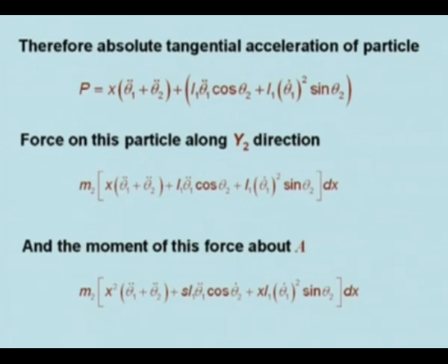Now the force on this particle along the y2 direction is m2 x(theta 1 double dot plus theta 2 double dot) plus L1 theta 1 double dot cos theta 2 plus L1 theta 1 dot square sin theta 2, into dx, because the mass of a small element at distance x is m2 dx.